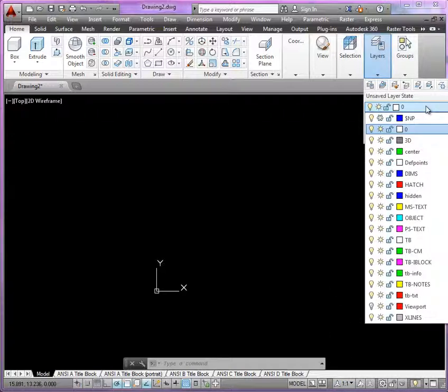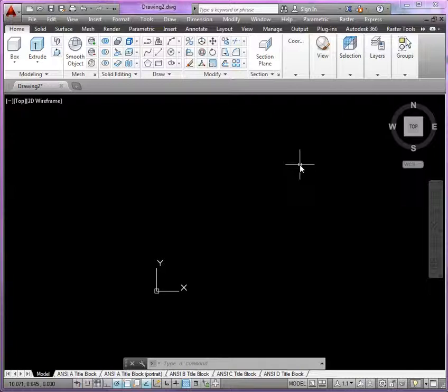And as you model, what you want to keep in mind is you're going to be using the 3D layer that'll contain all the solid geometry. And as you develop the solid views, you'll have to come back to your layer properties so that you can change the colors or check the line types for all of the newly created layers that occur with the use of solid draw.